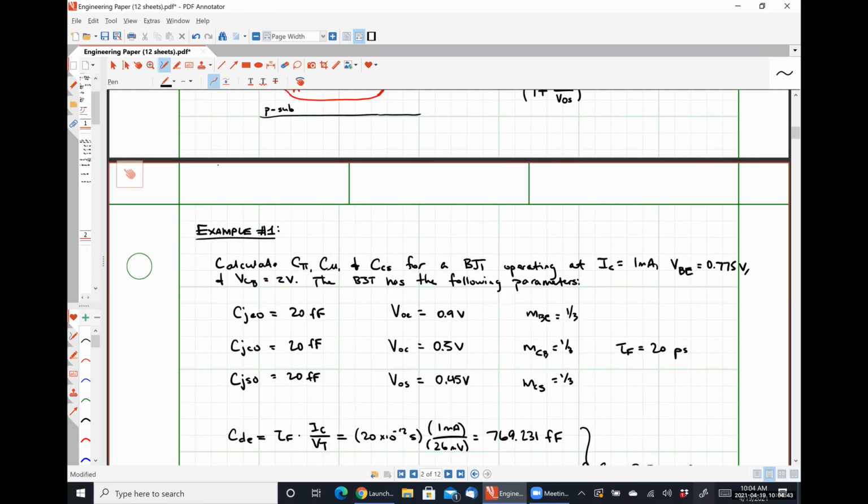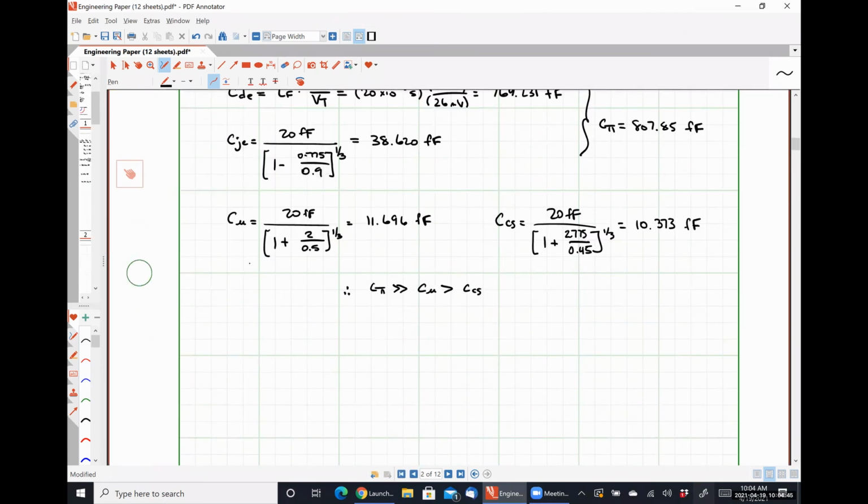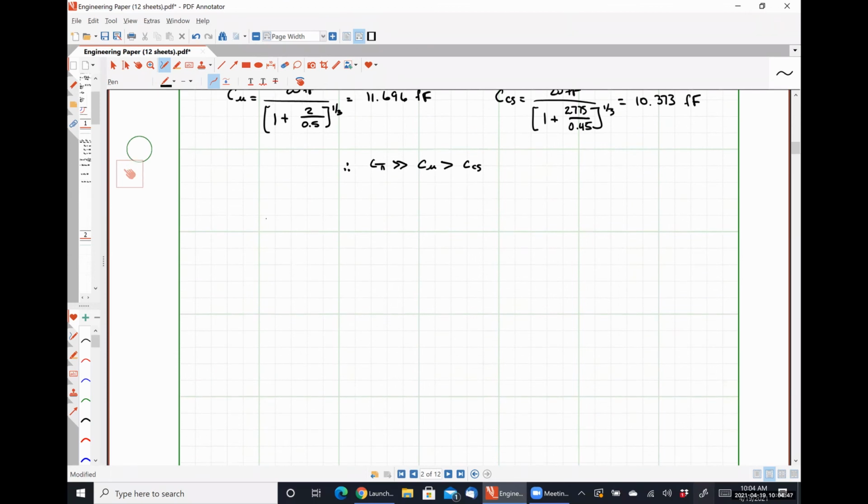So this is going to seem very unintuitive, but what we are going to wind up doing is creating an equation for beta as a function of frequency, and a consequence of that derivation will actually give us a method by which to calculate C pi, okay?